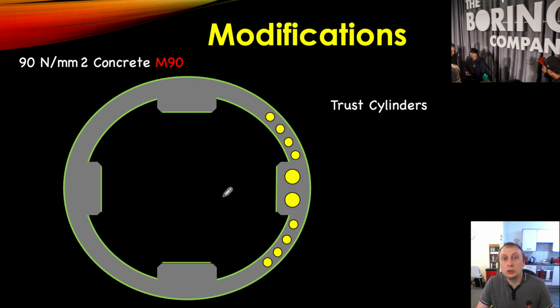One point as well that I just want to note while I'm thinking about it is when you are assembling these segments, the gaps in between segments, for example this gap here in between a segment and another segment, that needs to be packed out perfectly. If that is not packed out perfectly, we might as well not bother going with this design. So the packing of segments, however they intend to do that, needs to be done very, very accurately. We're just going to focus on straight lines, therefore the actual segments themselves should line up very, very neatly. The number of pressure points therefore is reduced, and by packing things out properly, and these larger enlarged areas here will make things a lot better for ourselves.